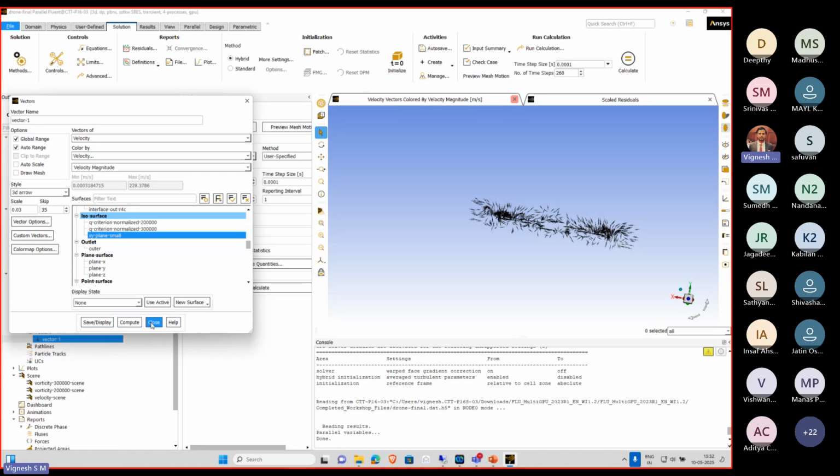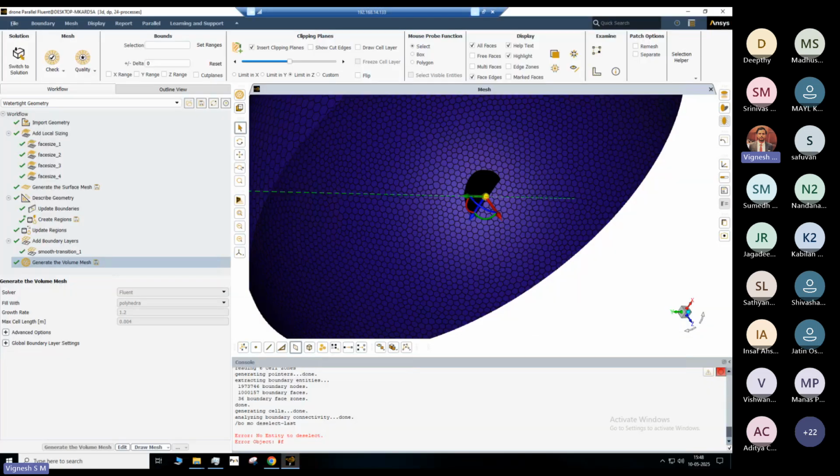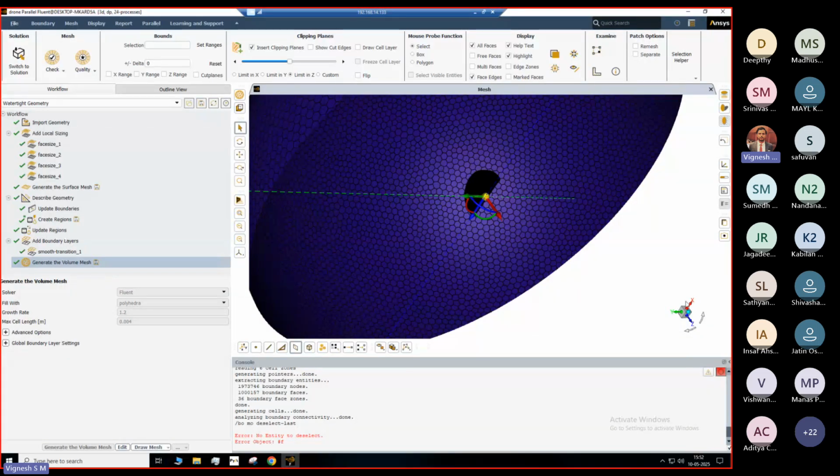By changing the propeller length, the pitch angle of the propeller, increasing the distance of the arms, or changing the RPM, you can understand how the aerodynamics of the quadcopter is affected. These are all the factors that we will change and parameterize to understand the aerodynamics of the quadcopter. And on the meshing side, it's better now.